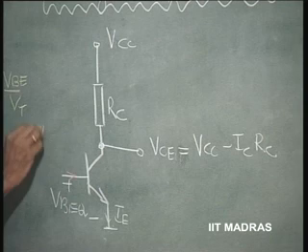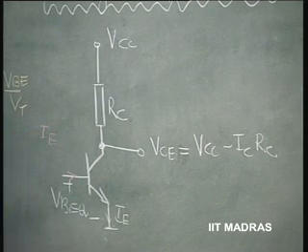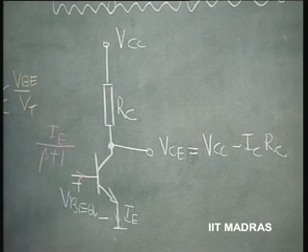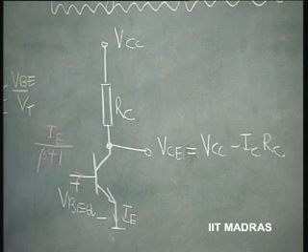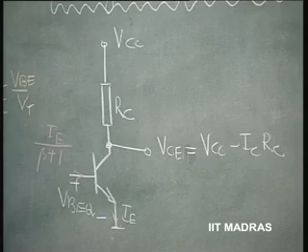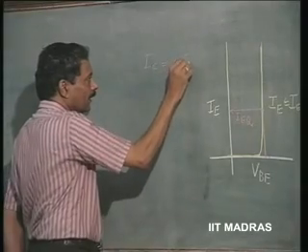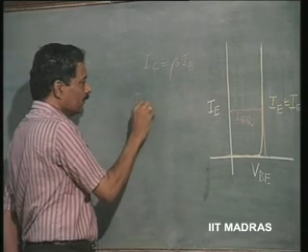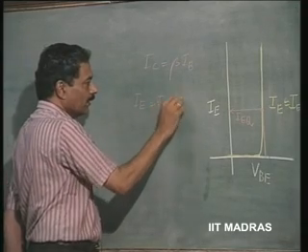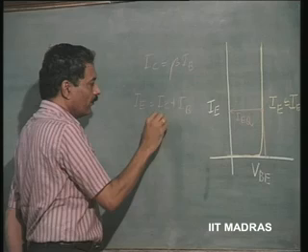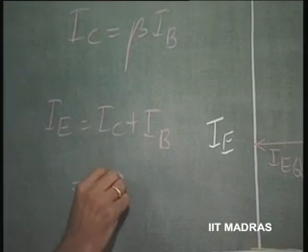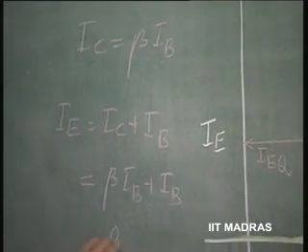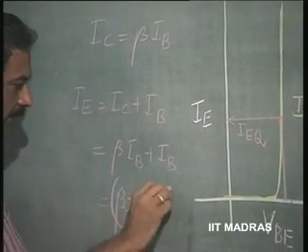So, for that purpose we said we will make a base current flow corresponding to IE. If it is 1 milliampere, the IB is going to be IE divided by beta plus 1. That is because IC is equal to beta times IB, and therefore IE is equal to IC plus IB. Therefore, we have IE equal to beta times IB plus IB, or it is equal to beta plus 1 times IB.